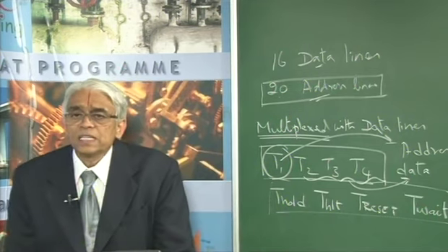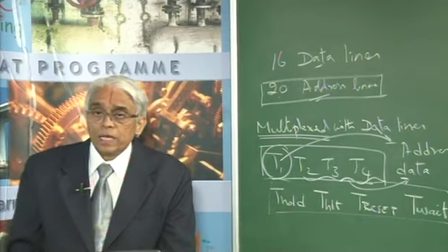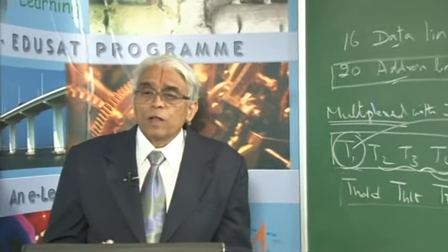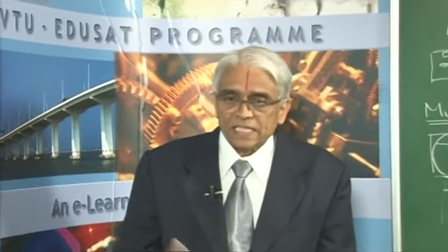Now, as the address is given only for a time, this address is going to be lost after the T1 period, and it has to be latched and stored somewhere. So, we have a signal, which we will talk about shortly, that enables the processor to take these address lines and send them to a particular latch, and this latch has to be designed by the user.